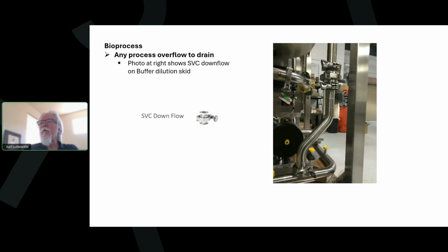And this one was used on an ILD system on what the customer described to me as an overflow line. It was interesting that this overflow line dumps into a horizontal sloped drain header that also is where the SIP condensate will drain into. And what gave me a clue to that was this little 1/2-inch tri-clamp fitting here.